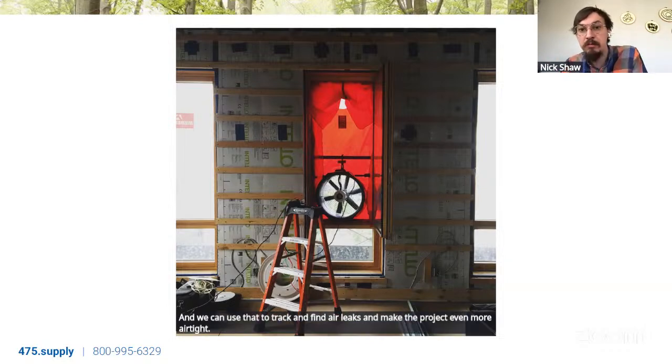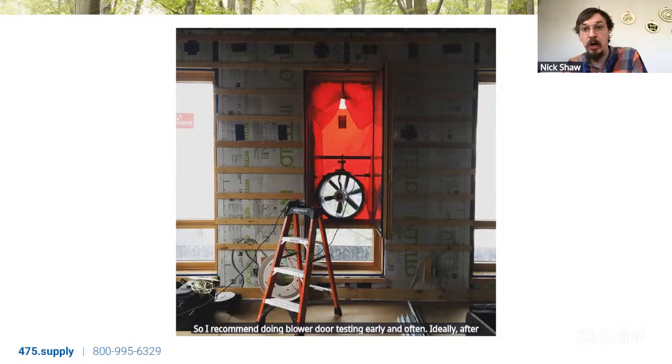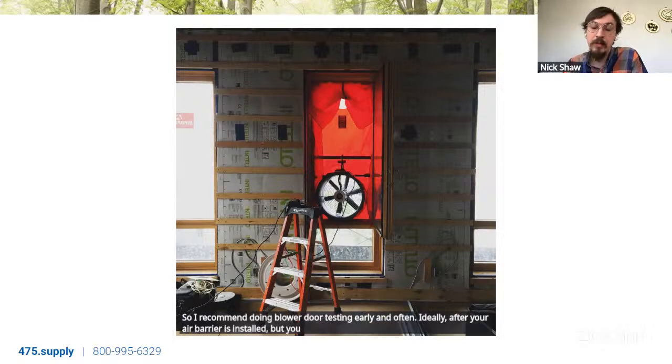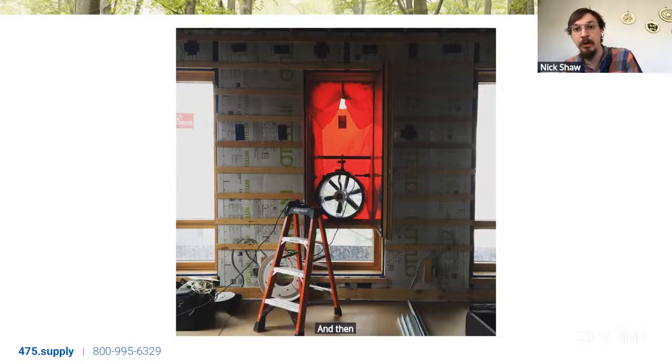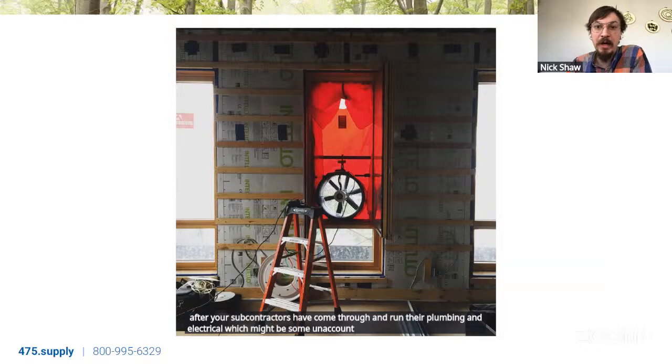So I recommend doing blower door testing early and often. Ideally after your air barrier is installed, but you still have access to it. And then typically again after your windows and doors are installed, ideally again after your subcontractors have come through and run their plumbing and electrical, which might be some unaccounted for air barrier penetrations.